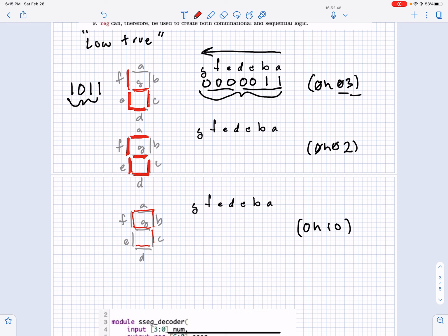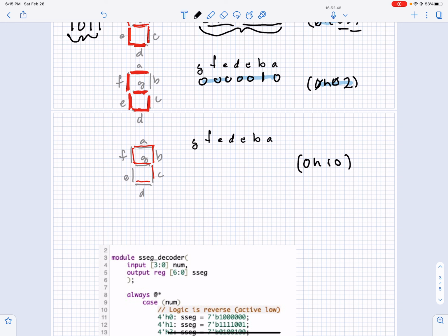All right, so if we had that, then what is our code? Well, we can go back and say I have all the same segments off, but so is A. The only thing that's not on is B, and we put a 1 there whenever B is equal to an off position. Okay, so of course we convert this to hex and we get 2. All right, and one more example. I'm going to do a 9. Typically, we would put a little tail piece on the 9.